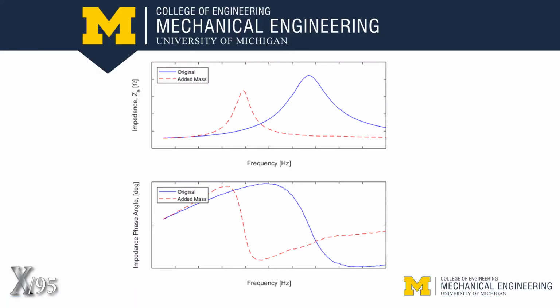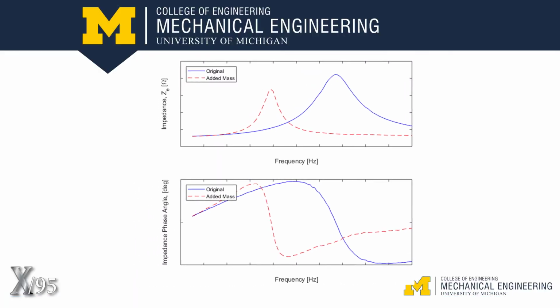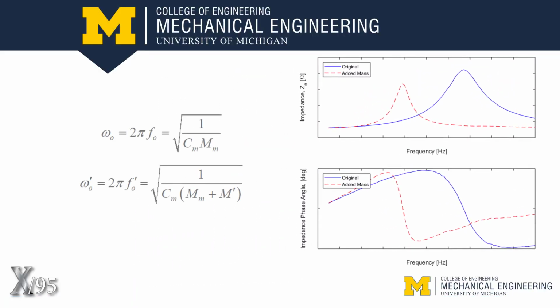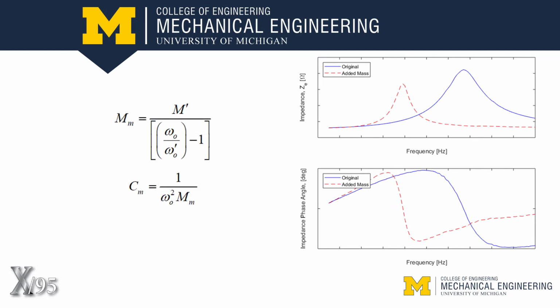Here's a Bode plot with and without the mass. Use the shift in resonant frequency to determine mechanical mass and compliance of the speaker.